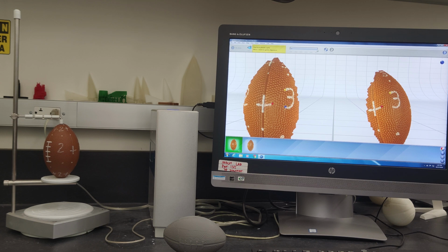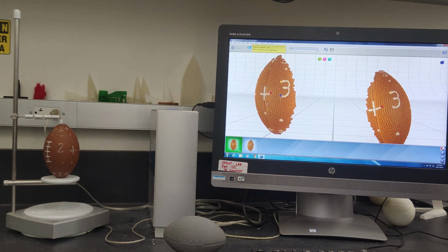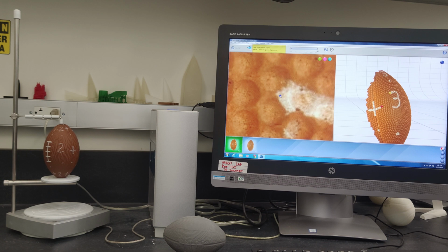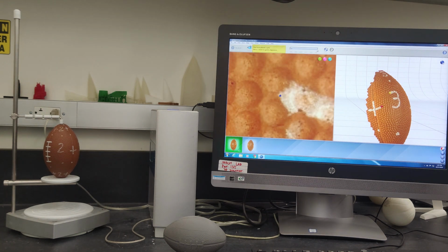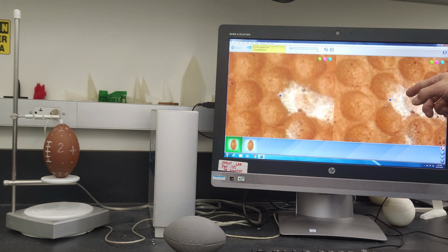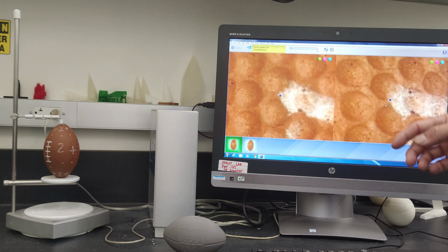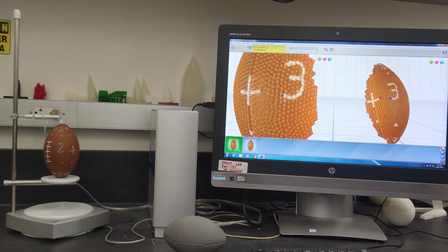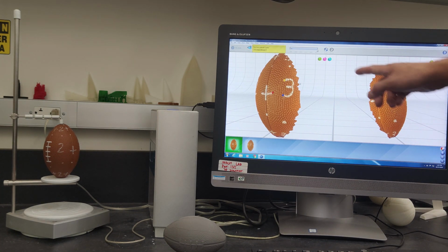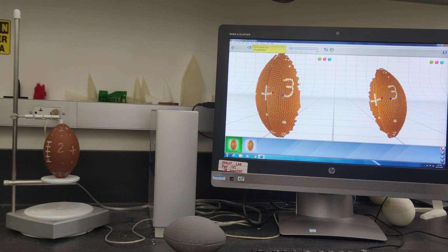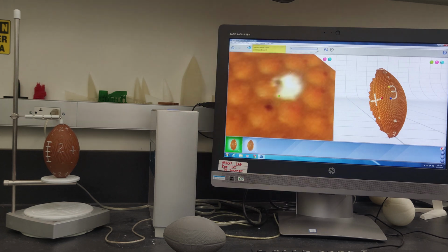Lastly, we are going to place the blue pin, and here is another suggestion. Try to place the pins in a triangle, not in a line. Otherwise, the software may not have enough information to combine the two sections in 2 dimensions. You may also notice there are 3 new pins with different colors on the screen, which means you can keep dropping more pins on the surface to generate a more accurate combination. Here I'm going to drop several more pins.